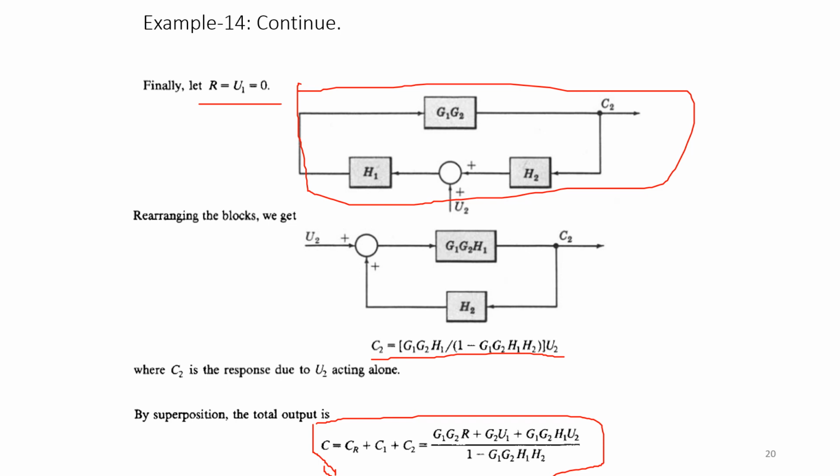I hope you have followed all the three examples quoted in today's session. I have taken three different examples. The first one was very simple, where we were applying the basic rules. Then in the second problem you learned how to apply the other rules, like shifting the takeoff point and summing point, and you analyzed how to reduce such complicated diagrams by identifying the suitable rules.